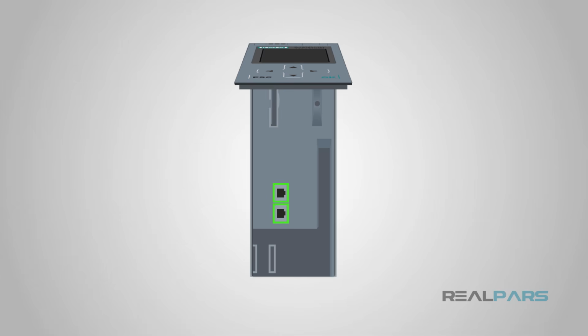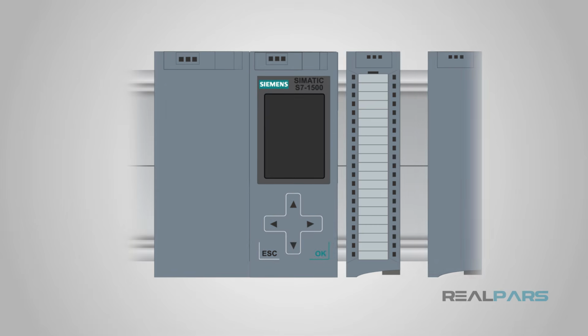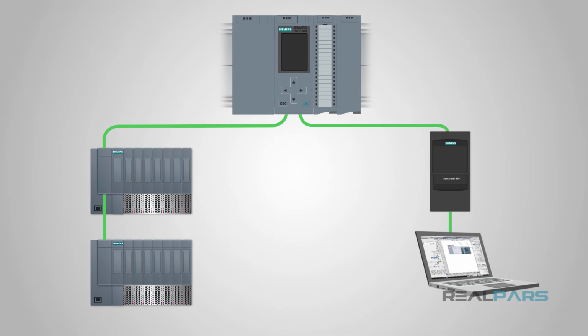Two Profinet ports come standard on every S7-1500 CPU, although you may select additional ports and communication protocols when ordering. As an added bonus, you're able to configure these ports as a bridge, which acts as a mini-switch. This can be very convenient when linking devices and interfacing with the PLC in the field. With S7-300s, the desired number of ports and appropriate communication protocol must be chosen up front. For both systems, there are expansion modules you can add after the fact to add extra ports or communication capabilities.